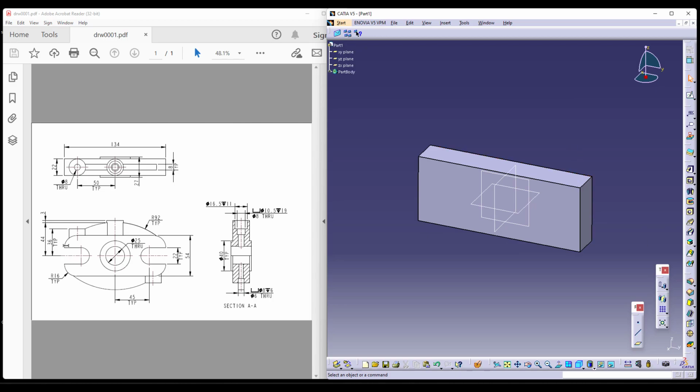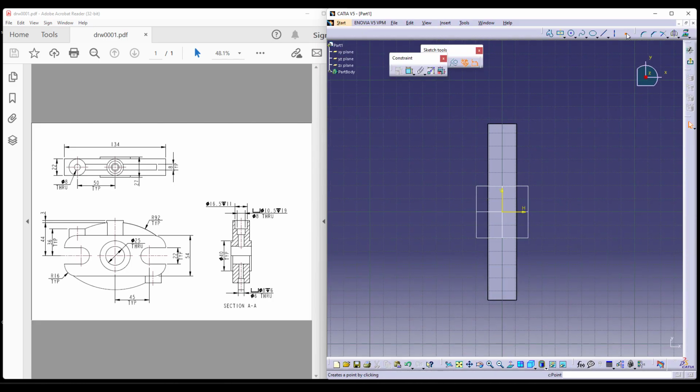Now, we have circles on the top, so we'll go one after the other. We need to cut this shape and add material. So instead, let us add material first and then go to the removing of material part a little later. As you can see, the distance for these extrusion circles are at 27. So if you want to maintain the dimension 27 and you want to make the model, we can use references. It is necessary that we maintain the dimensions because we are working on a feature based modeling.